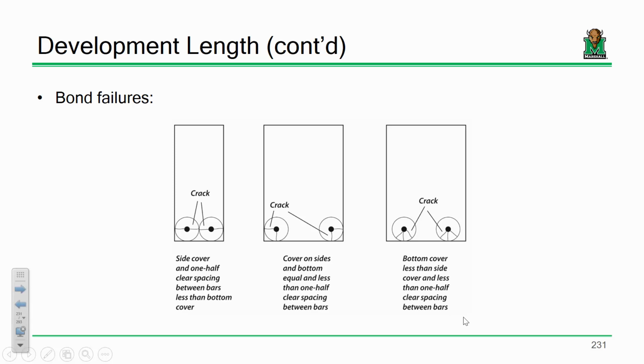Those cracks will continue to propagate until you hit one of three distances. You either hit right here, or right here, or if you have another bar over here, you hit halfway over. Because the idea is you're yanking on them all, so this one's going to be cracking as well. I just want you to keep these three distances in mind because they're going to pop up in a second.